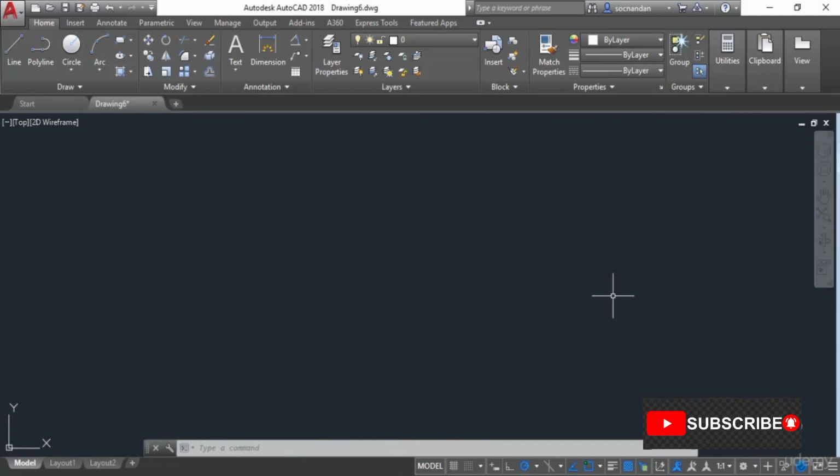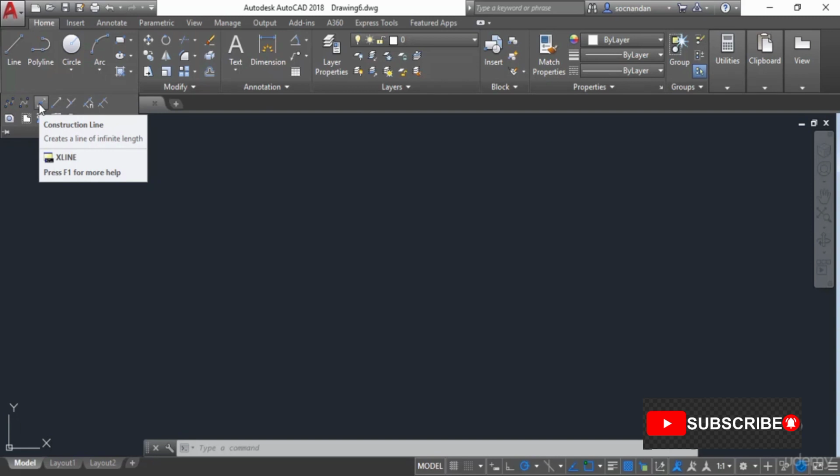In this video, I will tell you about the construction line and array command of AutoCAD. So construction lines are simply lines which are used for helping to make other geometries, and they are infinite lines. So to make the construction line, go to the draw panel, expand it, and now select this option here. So here we have this construction line.